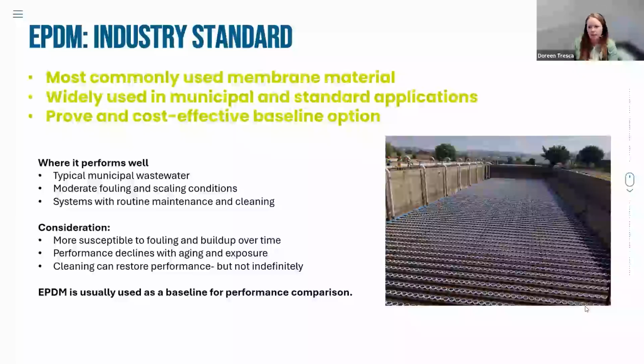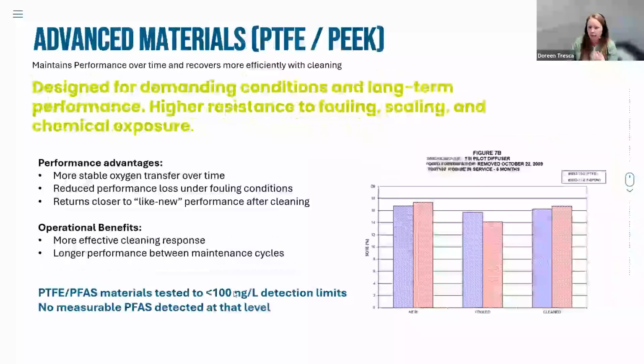Next, we're going to go into some of the more advanced membrane materials. At SSI, we offer both PTFE and PEEK membranes. Advanced membrane materials are a really good selection when you want something longer lasting or you have more demanding operating conditions. They do cost a little more, but they're typically used in systems where standard materials might struggle. These are very popular in industrial applications with higher chemical exposure or environments with more aggressive fouling.